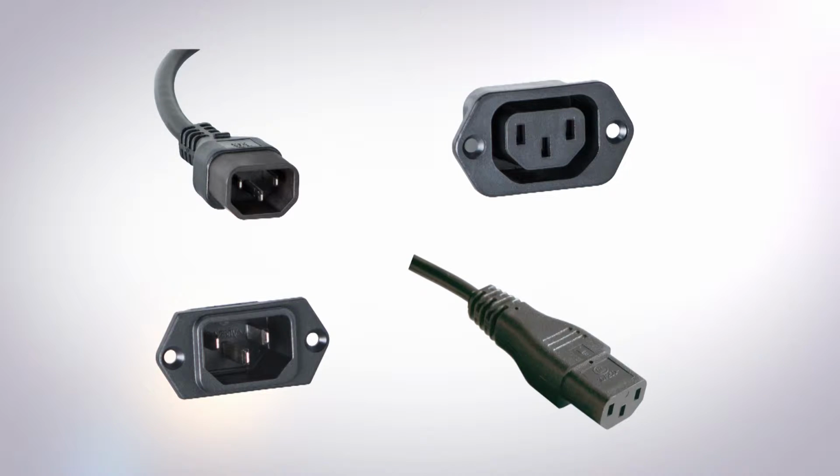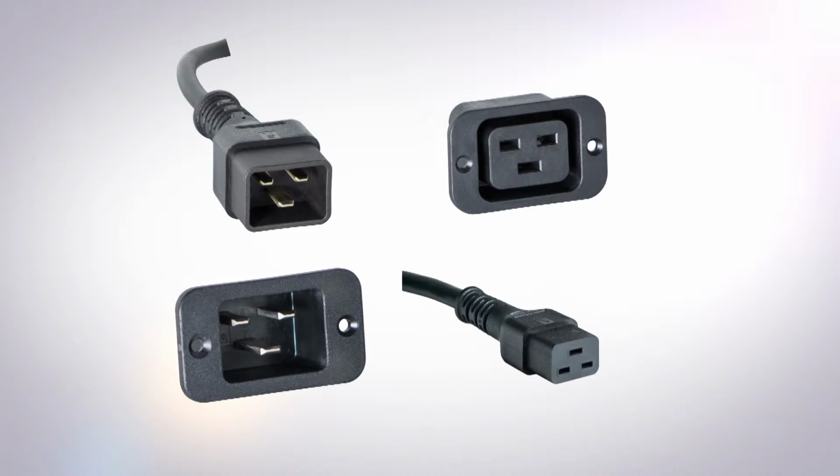The most common IEC 60320 accessory power configuration is rated 10 amps internationally and 15 amps for North American use. This includes items such as a Sheet E plug connector, Sheet F outlet, C14 inlet, and the C13 connector. Another very common configuration system in this family is rated 16 amps internationally and 20 amps for North American use. This includes the Sheet I plug connector, the Sheet J outlet, the C20 inlet, and the C19 connector.